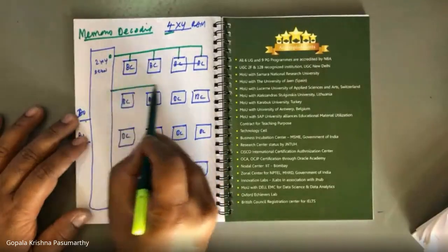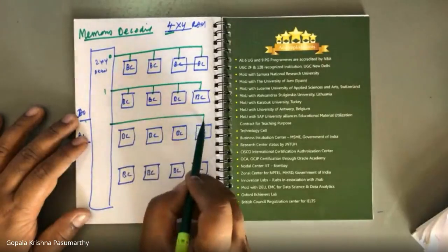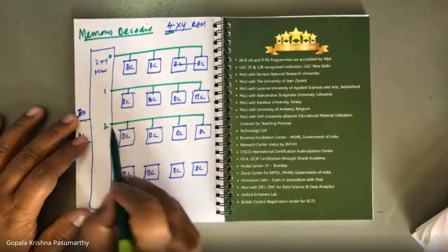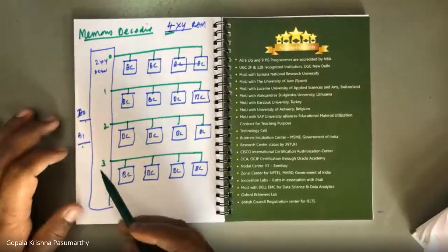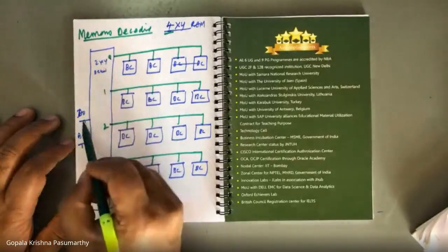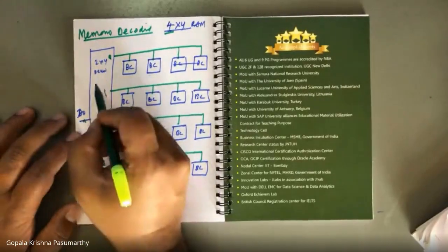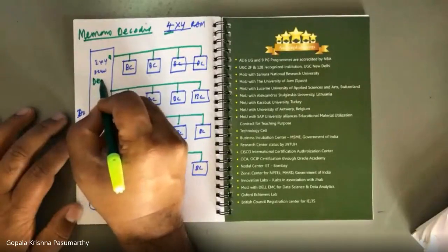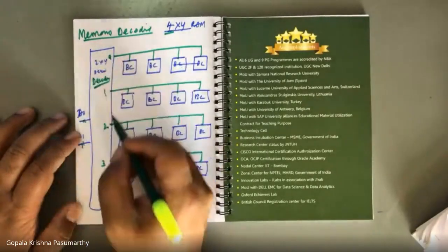Word 0, word 1, word 2, word 3. Because we know if you make A0 A1 as 0 0, word 0 is active. 0 1, word 1 will be active. 1 0, word 2 will be active. 1 1, word 3. Because this is a decoder.